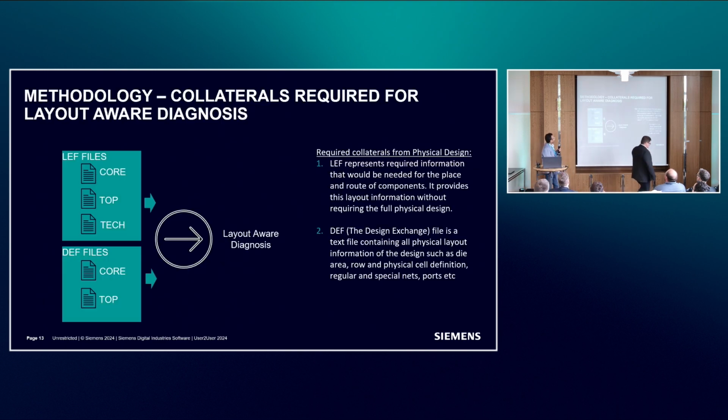Okay, as I said, for the layout aware diagnosis, the additional collaterals on top of what we've discussed previously in the diagnosis flow are your core level LEF files and top level LEF files. Tech files here means your memories or custom macros or standard cells. DEF file of your core and top is provided to the tool. And these are industry standard formats. You get them from any standard tools.